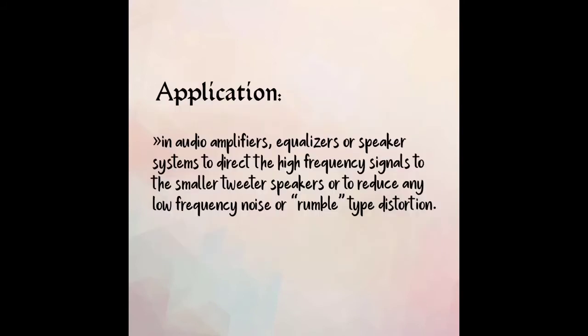One of the many applications of high-pass filters is that they are used as part of an audio crossover to direct high frequency to a tweeter while attenuating bass signals which could interfere with or damage the speaker. In short, high-pass filters are used for the removal of unwanted sounds near the lower end of the audible range. This experiment explains bandpass filter circuits.